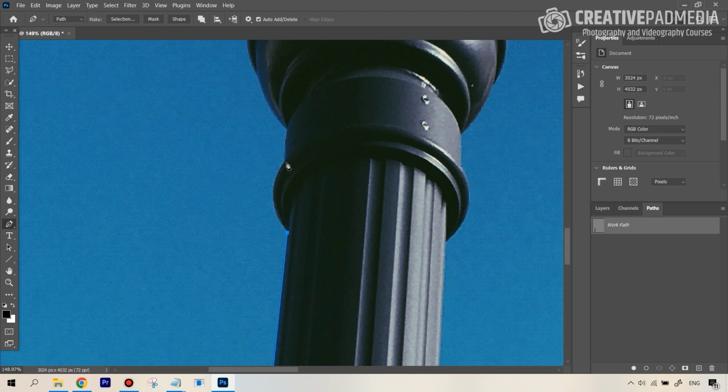What you want to do is place the next anchor point where this curve is ending, okay? So like this. But now I'm not going to click my mouse simply. I'm going to click the mouse, the left click on the mouse, and I'm going to hold it. So I'm not going to release the click, okay? So I place the anchor point, but I've not let go of the mouse. And can you see, if I don't let go of it, we get these handles, right? They will help us make this curve in any way that we want.